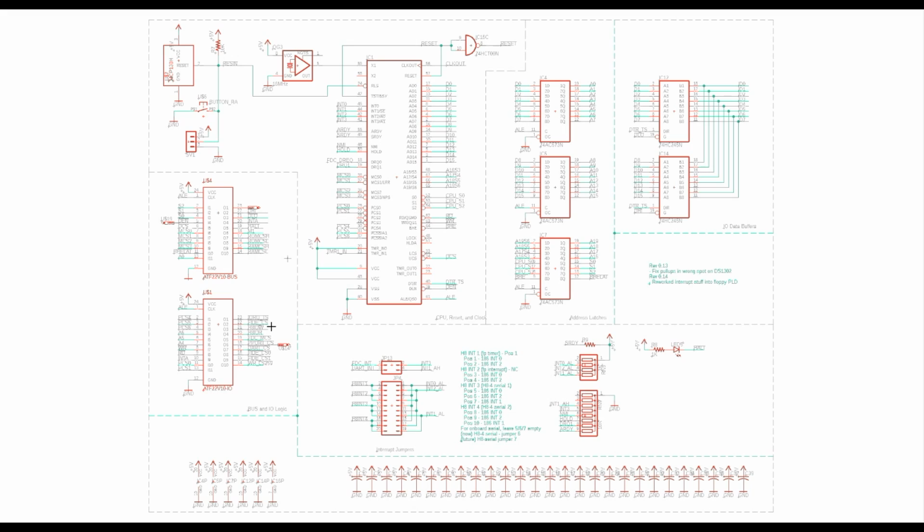The H8 bus is read and write. The floppy, the parallel. It's actually, we don't have the parallel port, but I still left it marked as parallel port. The UART and the IDE and the latch for the diagnostic LEDs. Now down here, we have some stuff for mapping interrupts.